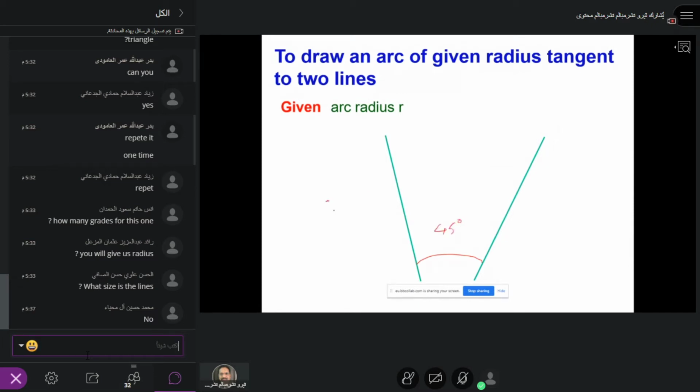You just take a small point there and draw this line at 45 degrees, and I'll give the radius, let's say 10 mm. Then if you take this 10 mm radius here, draw the line, and another radius here, the same 10 mm, draw the line here. So this will be meeting at this point. Then by using the tri-square, draw the perpendicular line from here and the perpendicular line. So this joins here. Take this as the center, this as the radius, and draw the arc.